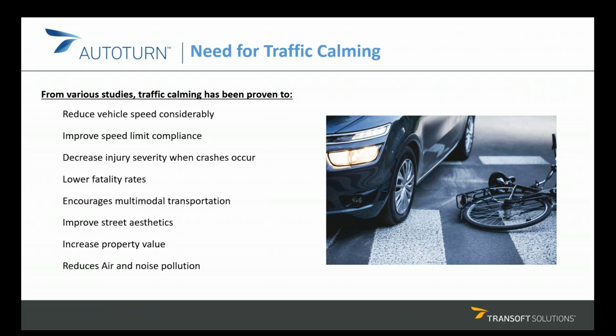Various studies have shown that traffic calming can reduce vehicle speed and volume considerably. Some regions found a drop of more than 10 to 16% in the total traffic volume, and found that more vehicles were traveling at a lower speed, which is less than 23 miles per hour or 37 kilometers per hour, after the implementation of traffic calming measures in various regions.